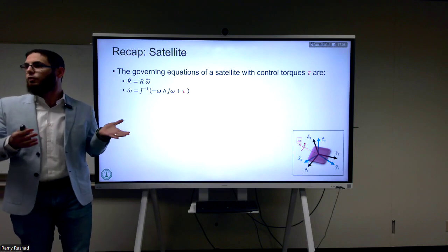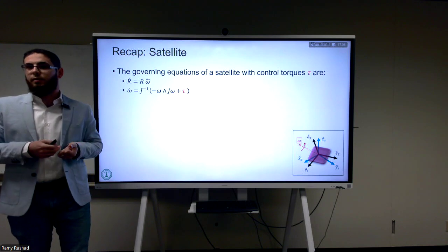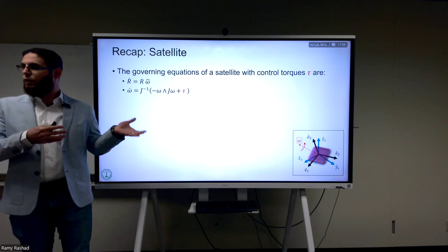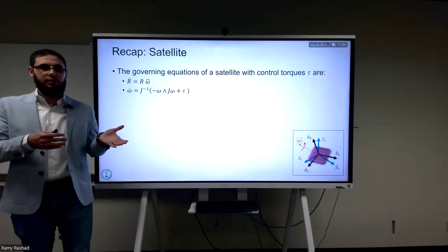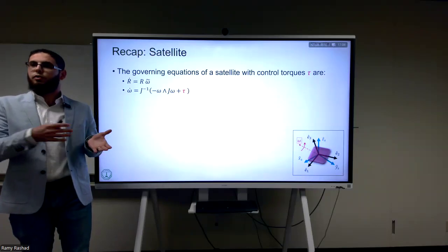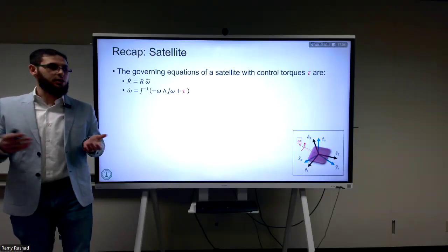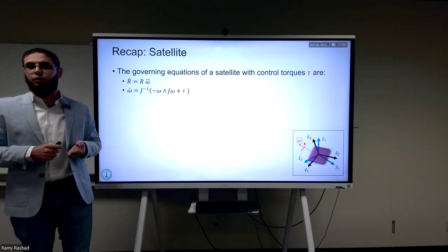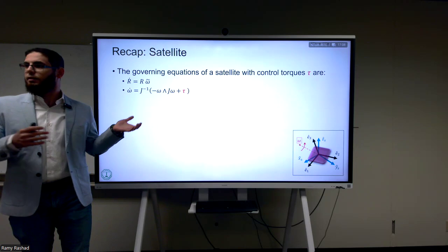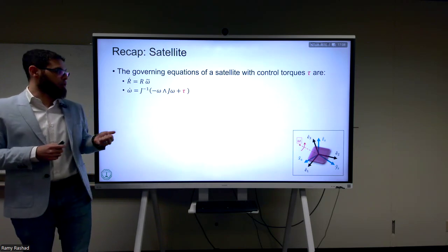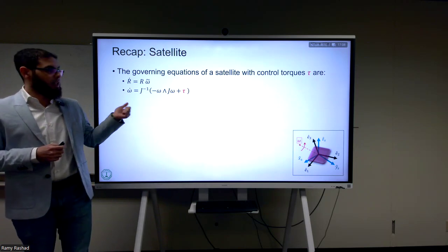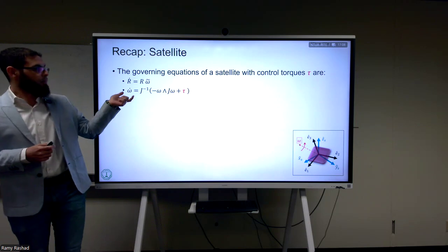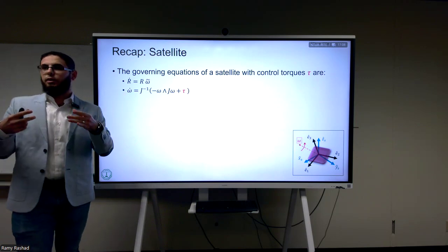And this is not just any manifold, this is really one of the most fundamental manifolds. It's part of SE3, actually the hard part of SE3. So if you can do control on SO3, SE3 becomes an easier task. Sometimes it's trivial. If I have some time, I can show you in the end. Sometimes it's more complicated depending on the application. We're going to be looking at both, inshallah. But now we're just considering SO3, a prototypical example.